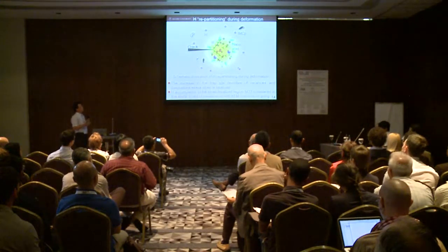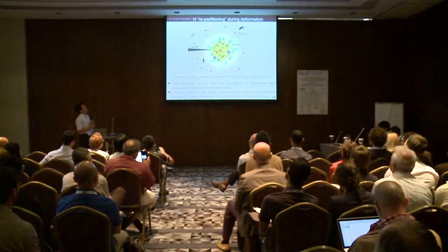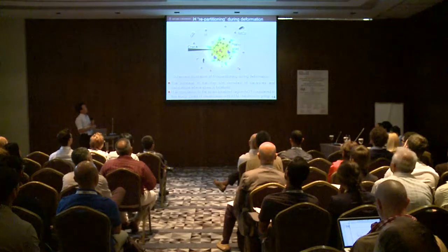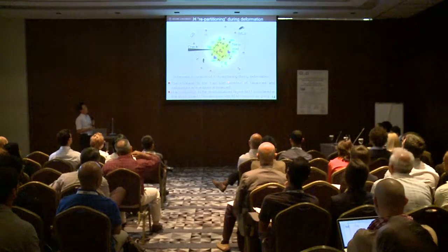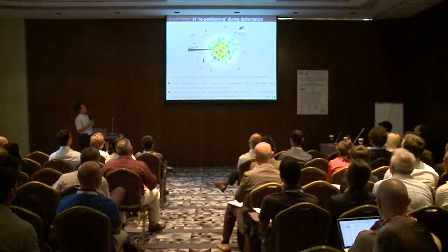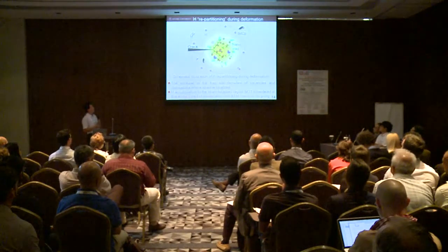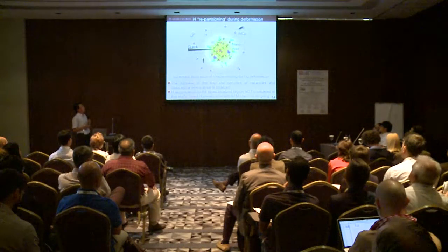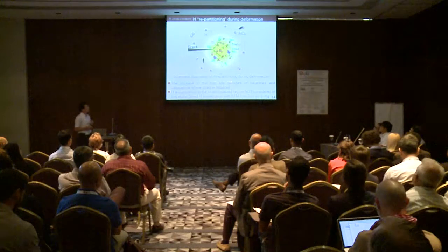So we would like to analyze this behavior in this way. We assume the hydrogen repartitioning occurs during deformation. The crack is coming, and there is a crack tip area. And then hydrogen trap site densities, such as vacancies and dislocations, may increase during deformation. And also hydrogen comes in from the outside to the inside of the strain localized region. Although we don't take this hydrogen accumulation into account in this study, we are going to see this behavior by taking a look at the in situ increase in trap site densities.